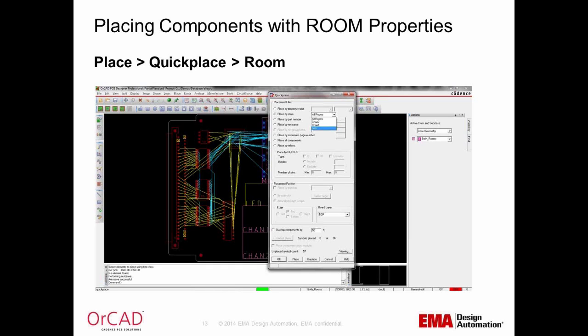The plus or minus coupled tolerances are tolerance values that are applied, either added to or subtracted from, the gap values. The minimum line spacing is the line-to-line check that ensures the primary gap minus the negative tolerance does not fall below the minimum line spacing required for your board.